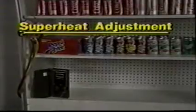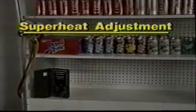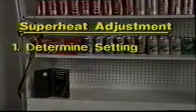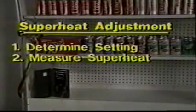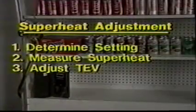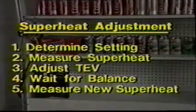Let's look at the whole superheat adjustment sequence again. First, determine the desired setting. Next, measure the existing superheat. Adjust, wait for balance, and measure performance.